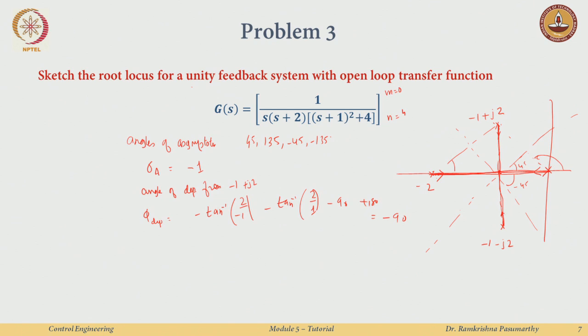So, something interesting is happening here. Everybody is meeting here, that is what it seems like, and then what do they do after they meet here? Well, now let me compute the breakaway points, again by setting dk by ds equal to 0.